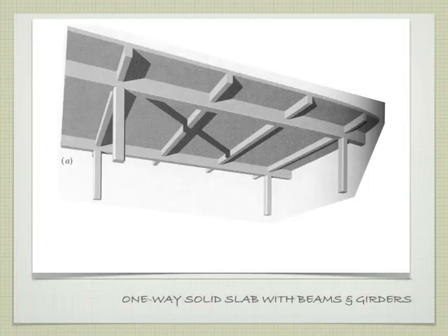And so this is still the one-way slab, even though it has a crisscross of beams. Okay, and so if we look at this carefully, we have our column that's supporting our long beam here, which would be called a girder. The use of girder and beam is somewhat interchangeable. Girder is always the largest, beam would be the next size down, and joist would be the next size down. It just works in that order, though oftentimes you'll refer to something like a girder and call it a beam, right? So they get a little bit confusing, but I just want you to know the general order.